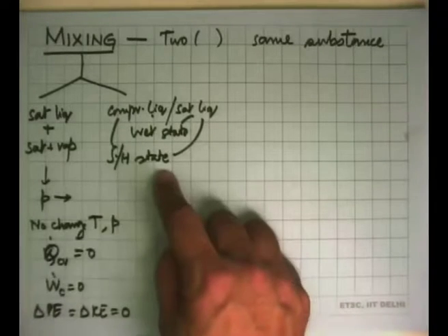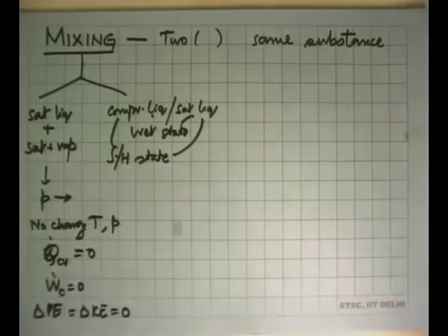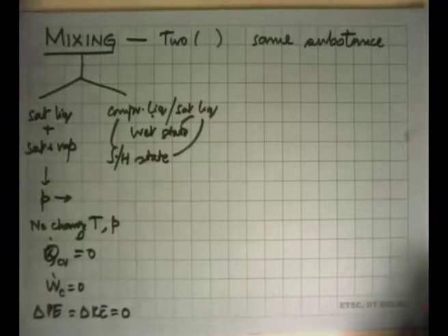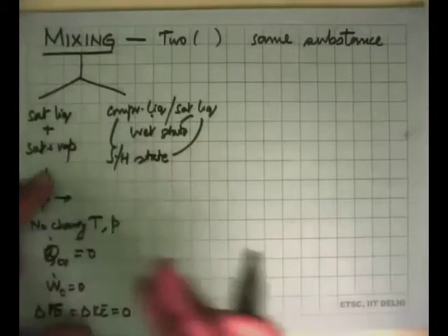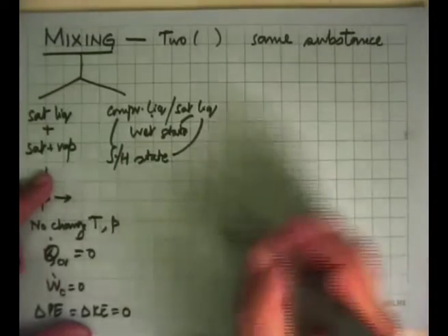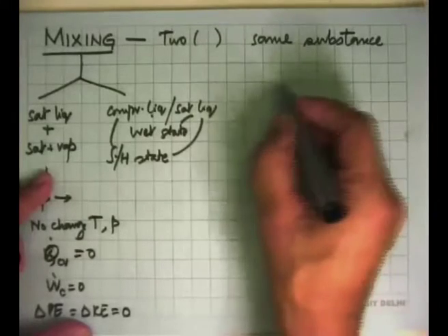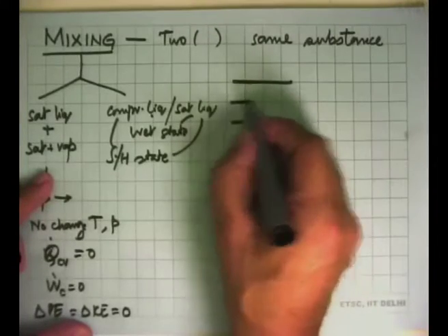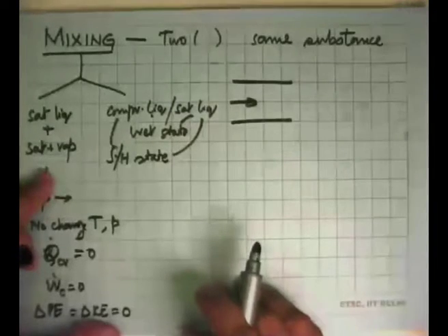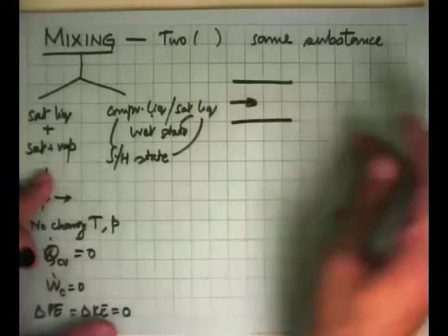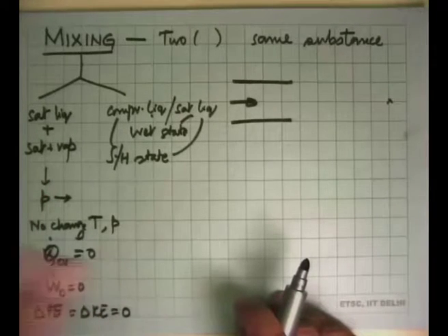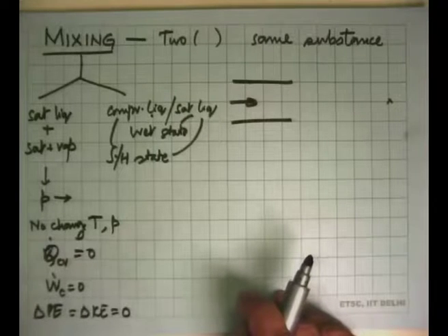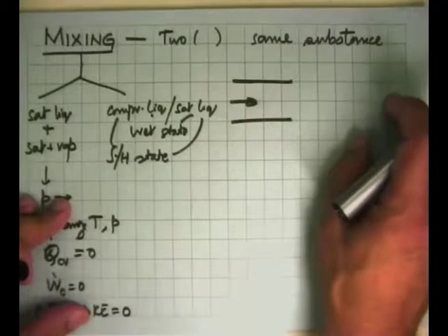In this case, this will not be true. It will come to some other state. So let's say for practical example, and then we will see on the property diagram what actually happens and why we are even considering such a situation. The one thing is that if we have, say, superheated steam or any other substance going through this, like say superheated, if we want to control and maintain its pressure, the device to use is a pressure regulator. So it will throttle it. So you can only reduce the pressure and maintain it constant. You cannot increase it.